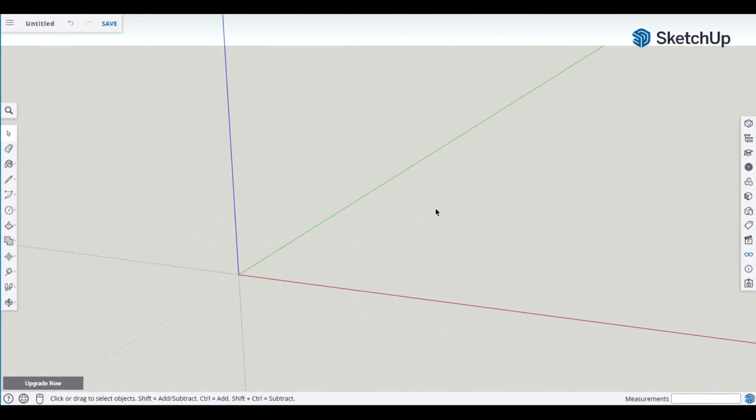All right, so let's start with making the legs for the table first, and that's going to consist of a rectangle. So we can select the R tool. We're going to make it 2 inches by 19 inches. And if you look at the bottom right, you can see that the first dimension will be the width. So we're going to type in 2, and then we're going to type in 19 inches for the length of the leg. Hit the space bar.